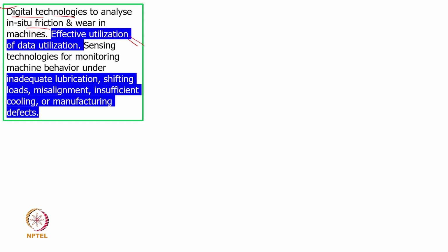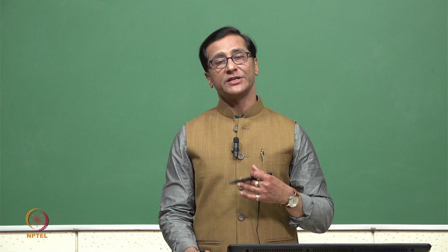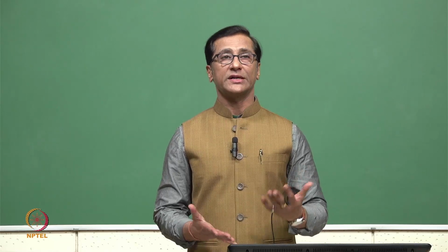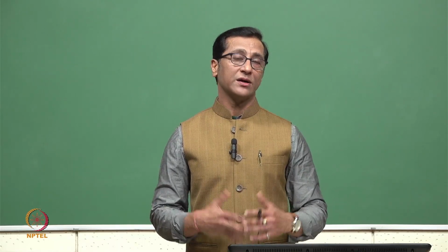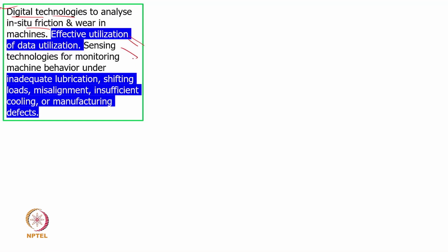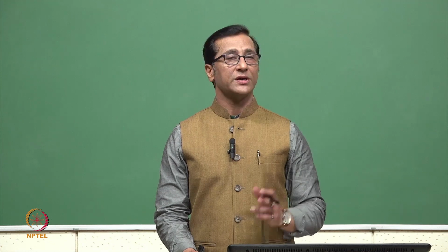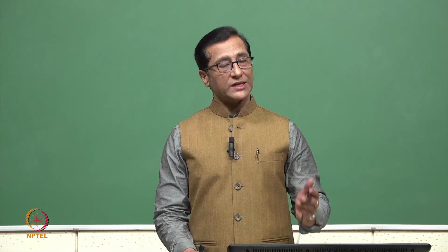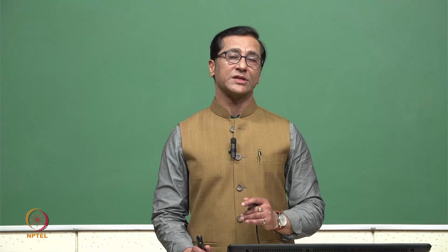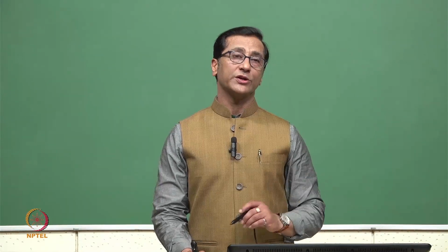We don't have to do everything or just take a judgment well in advance. Whatever data comes, we need to analyze those data, and then we use the sensing technologies to monitor the machine behavior under different conditions, whether there is insufficient or inadequate lubricant. If there is inadequate lubricant, naturally temperature rise will be there. So either we have a thermocouple or we have a thermal imaging camera, then we can do it.